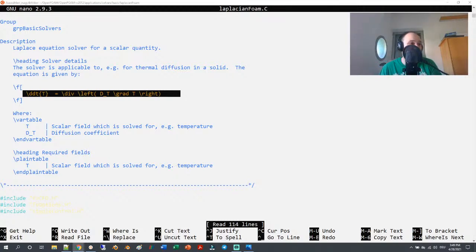Now, commercial, I know that, for example, layer addition is problematic in OpenFOAM, and in some commercial codes it's much better. If you are really interested in the near wall behavior, then a commercial mesher is maybe better, but I know that for cfMesh the layer addition is a bit better. So before I'd go for a commercial mesher, I test snappyHexMesh and cfMesh, whether they can create decent layers on your walls, and if they fail, then I would go to a commercial mesher.